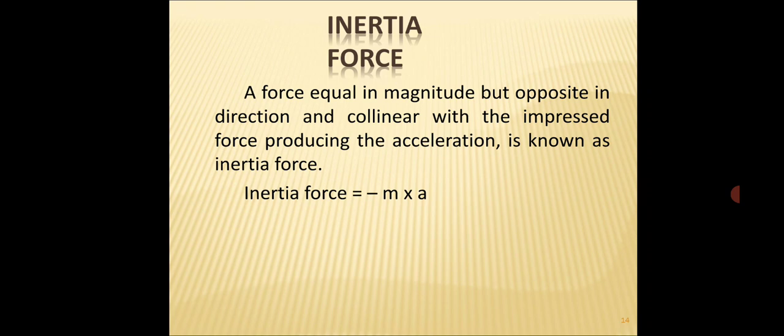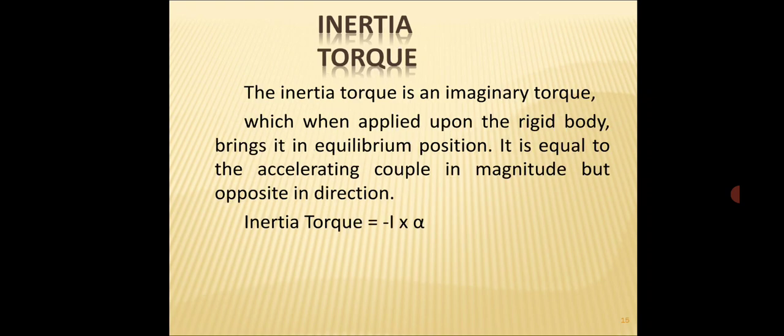So what does inertia force mean? A force equal in magnitude but opposite in direction and collinear with the impressed force producing the acceleration is known as the inertia force. Here the inertia force is mass into acceleration. Next is the inertia torque. What does inertia torque mean? The inertia torque is an imaginary torque which, when applied upon a rigid body, brings it into equilibrium position. It is equal to the accelerating couple in magnitude but opposite in direction. So this is the inertia torque.